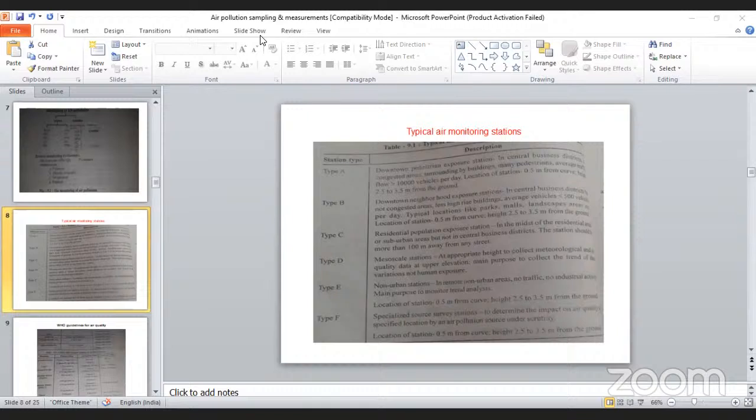And 5 main characteristics for the air sampling system are collection efficiency, sample stability, recovery, minimal interferences, and understanding of mechanism of collection. If we are not understanding how we will do that, because now whatever method we are talking, this is not analysis, this is only collection of sample. Collection of sample, we have to take this much precautionary action, and we are supposed to be provided with this kind of technical facilities. Then only we do.